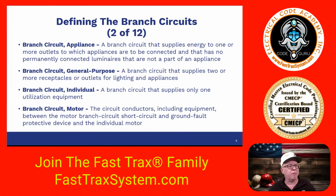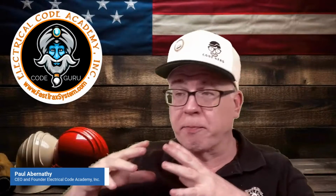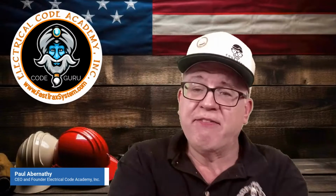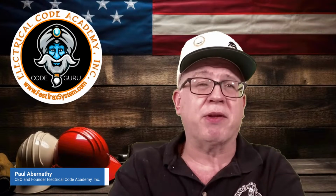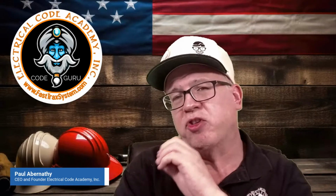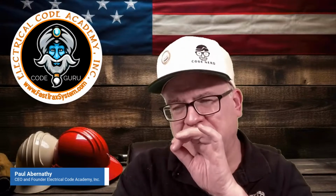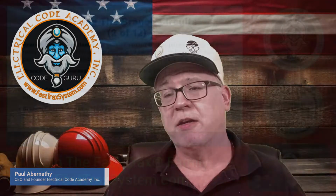Let me give you an example. So let's say I had a requirement to have an individual branch circuit to a receptacle for whatever piece of equipment that's going to be dedicated to that receptacle, and the engineer specifies that. Well, if that's an individual branch circuit, we couldn't put a duplex in there because something else could be plugged into the other receptacle. If it's only for that piece of utilization equipment, whether it's cord and plug or hardwired, we have to do it in a way that that is the only piece of utilization equipment that can be connected to that individual branch circuit. So that's an important distinction to be aware of.